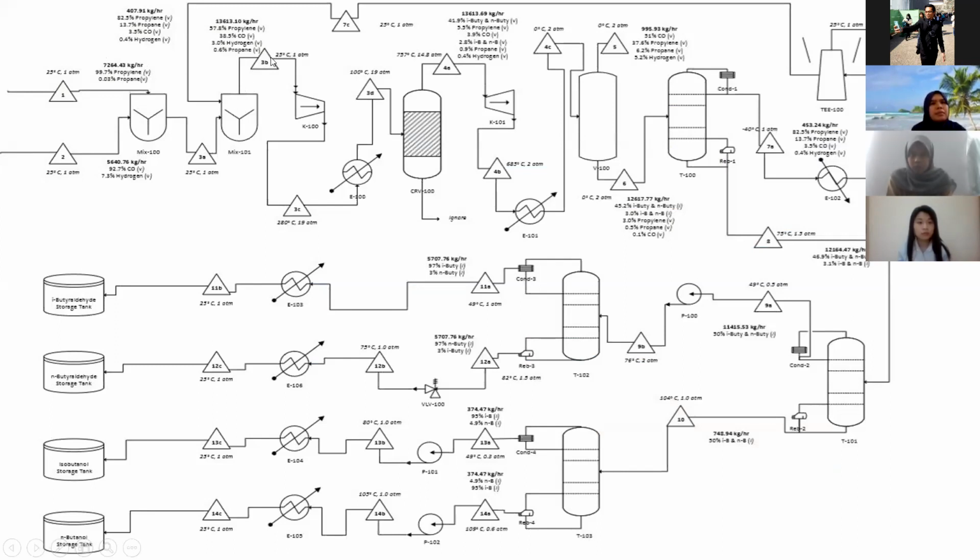The outlet stream of this second mixer will be sent to a reactor, CSTR, operating at 100 degrees C and 19 atm. To match this operating condition of the reactor, the outlet stream of the mixer will undergo temperature and pressure changes via a compressor and a cooler.